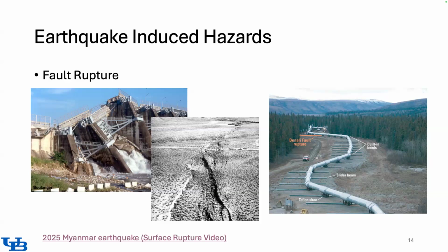But as engineers, we can be clever about it. One of the things that we want to be able to understand through this course is, if this is to happen, what solutions can we propose to avoid it? For example, for liquefaction, we can think how we can densify the soil or how we can add drains so that pore pressure doesn't increase.